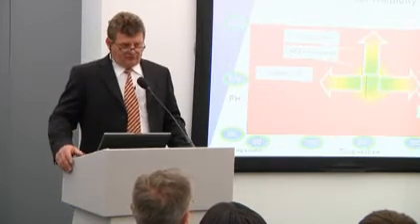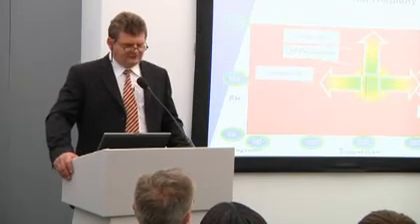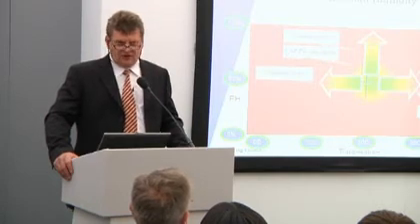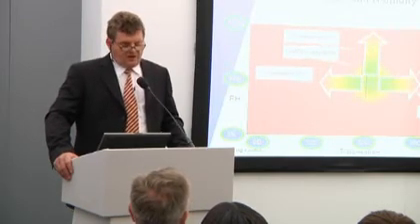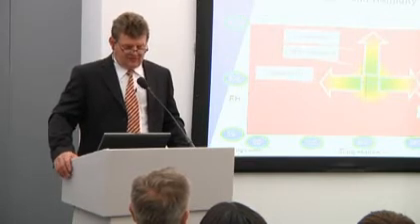With printed circuit boards, there is also an issue of a thing called CAF development, which is a filament development which can grow on printed circuit boards and can cause failures. But that only happens at high temperatures and very high humidities.